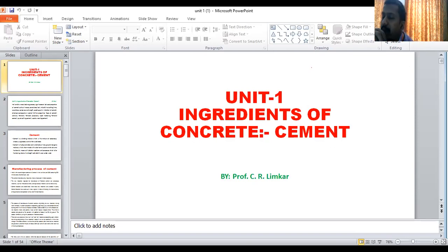The strength is nothing but the ratio of the load which is acting on your particular material, whatever it may be, the mold, it may be the concrete cube, or it may be your reinforcement. So the load which is acting divided by the area, that will give you the strength for that particular cement mortar. Okay, load divided by area.